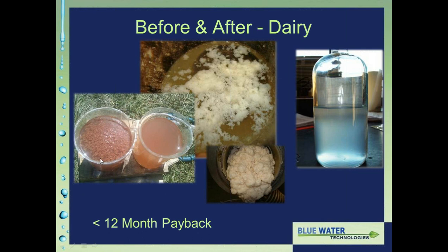You can see raw water. This is actually a whey digested stream, but it requires polymer. As I mentioned before, very few of our applications do require polymer, and most of them that do are industrial. So you can see the level of clarity that you have after treatment. This was actually a sample grabbed after treatment on a pilot scale.